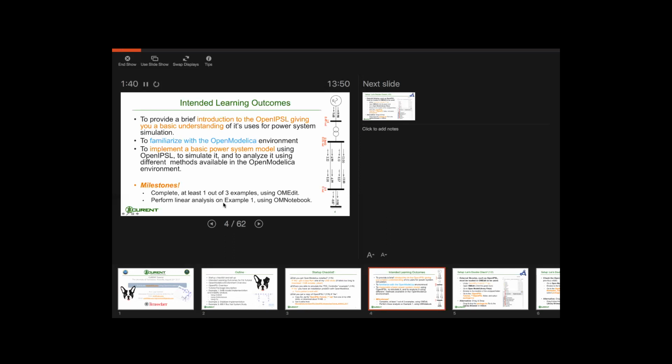One thing that is very common in power system tools is that you only get the nonlinear simulation. You don't get the linearized model. With Modelica tools, you can get the linearized model for free. And that's very powerful, because now you don't have to use two different software or re-implement all the equations. You just define yourself the inputs and outputs. So if you want an internal state that is not measured, you just pick it up and define that that's what you need to do.